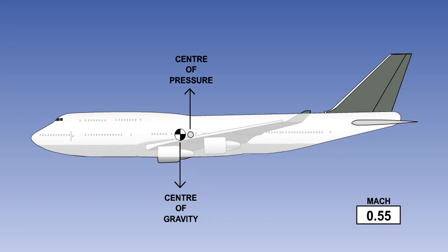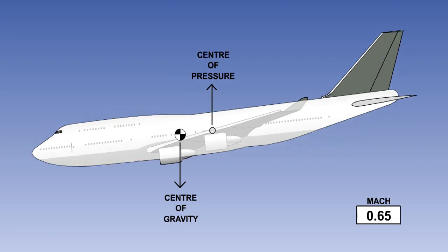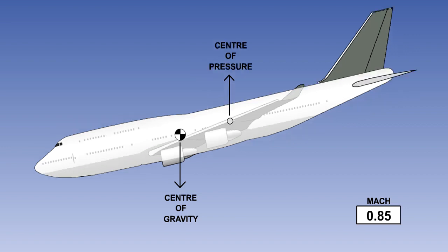On most large turbojet aircraft, the wing centre of pressure moves rearward as the aircraft approaches high subsonic speed, and this produces large nose-down pitching moments, known as tuck-under or Mach tuck. It is essential that the aircraft is fitted with an automatic system to correct this change in pitch attitude. Such a system is known as Mach trim, and is designed so that it will operate whether or not the autopilot, or some other method of automatic flight control, is engaged.